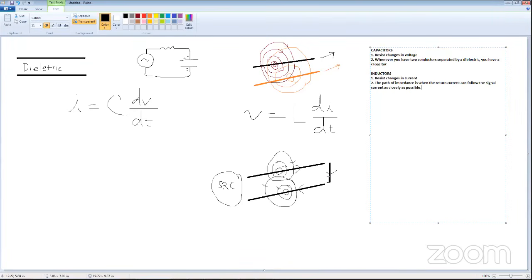So keep that in mind when you're laying out your boards and doing your power planes. Try to leave them as solid as you can and try to route your traces in such a way that if you have anything sensitive, there's no return current path running on the ground plane that could collide or interfere with yours, since that will create some additional noise.